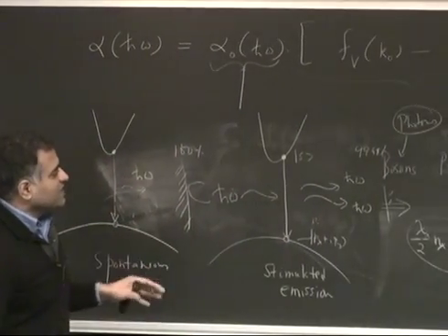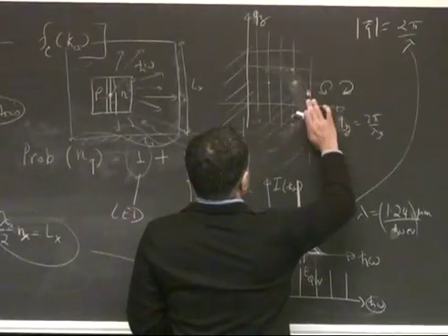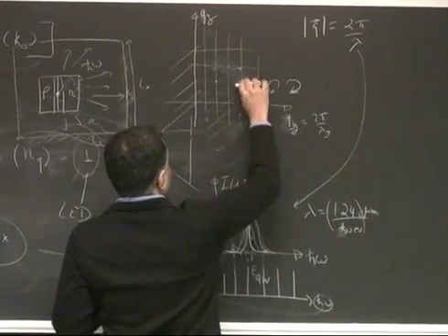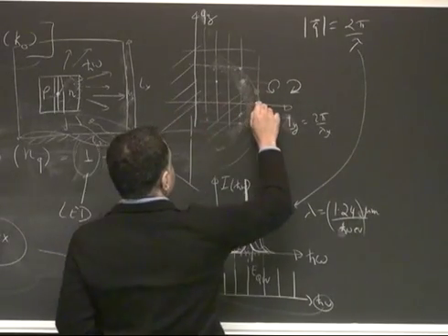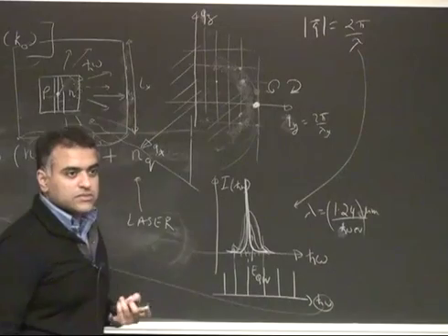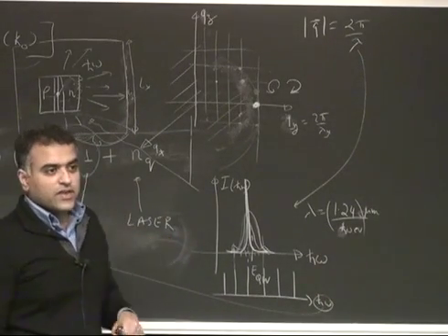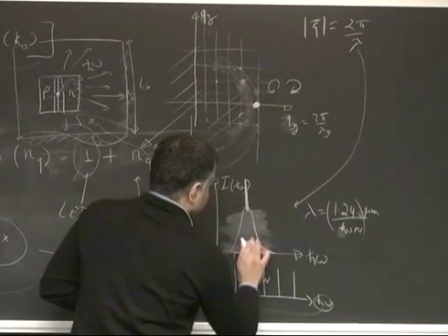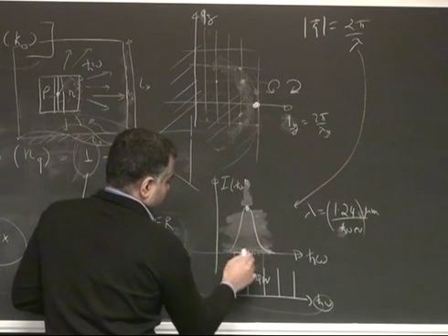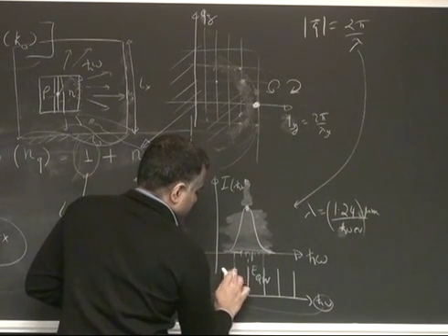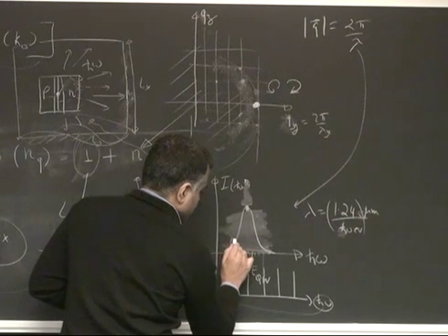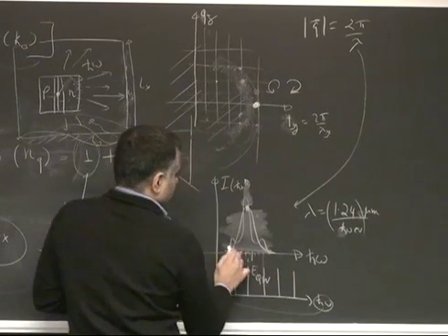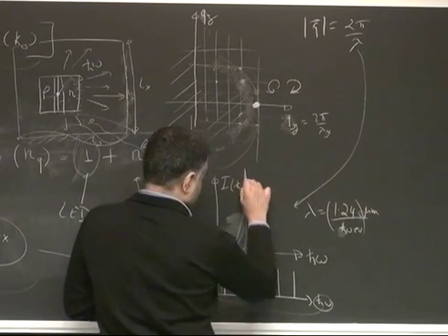So what is extremely important in the laser? The end result is that in a laser, as opposed to an LED where you have a bit of a cloud of modes into which the light is emitted, you will typically want only one. All of the light goes into only one. Initially, when it's just about to start lasing, you have electroluminescence like this, with multiple modes. And once you cross the threshold of lasing, that's when you get only one peak.